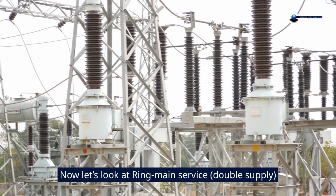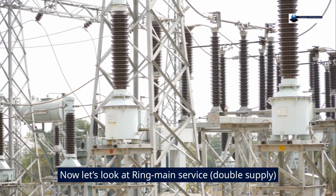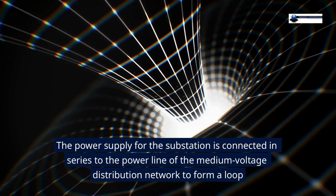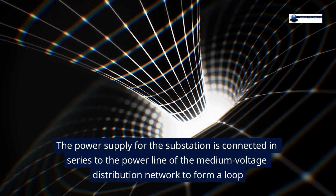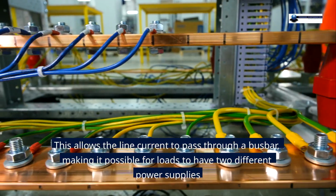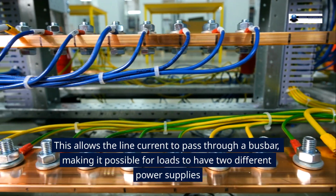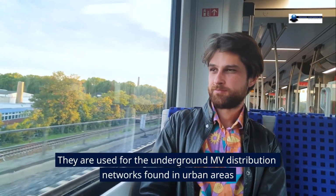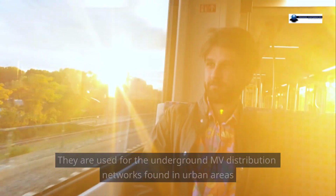Now let's look at ring main service, double supply. The power supply for the substation is connected in series to the power line of the medium voltage distribution network to form a loop. This allows the line current to pass through a bus bar, making it possible for loads to have 2 different power supplies. They are used for the underground MV distribution networks found in urban areas.